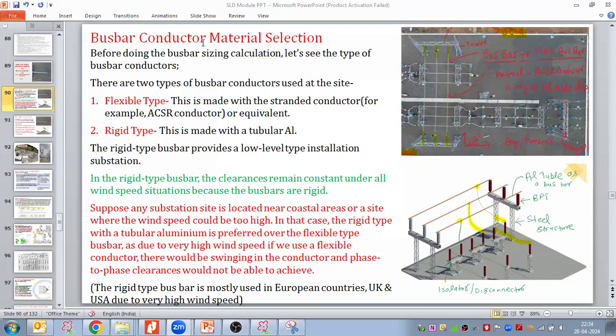Sir, I have normally seen that in the main bus, we don't use CVT, we use PT. So what could be the particular reason? Is that the precision? PT we use till 33 kilovoltage, and if you are going above 33 kilovoltage and you use the PT, it is not economical in cost. You are paying higher cost for that purpose.